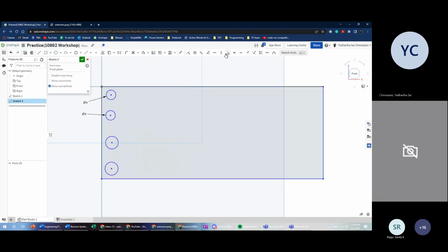So basically what these tools help you to do is to reduce that, right? So I can make the circle and the circle equal, and look how the circle is just equal. And if you want to know which circles are equal to each other, you could hover over the circle, and hover over the equal sign, and it'll tell you which circles are equal to each other. And I use this a lot. I'm stressing a lot about it, because it's really an important tool that people use.